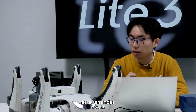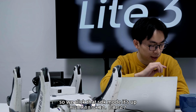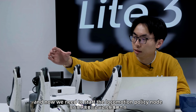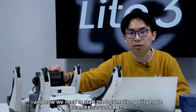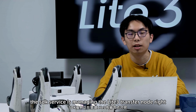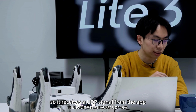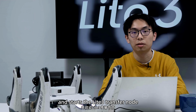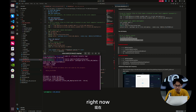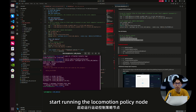So as a reminder, right now we have already started the transfer node on the robot, right? So we click that STK mode, it's up, and now we need to start the locomotion policy node. So what we just did here, the STK service is managing the Lite3 transfer node, right? So it receives a UDP signal from the app and starts the Lite3 transfer node. So this is what it's been doing. Right now, we are trying to compile and start running the locomotion policy node.